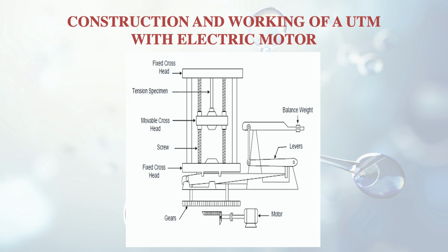If it is pushing it towards the bottom, then it is compression, and if it is acting transversely, then it is shear. And if the load is acting transversely and it is fixed at one end, then bending can also occur. So these are the various kinds of loads that are acting on the specimen.